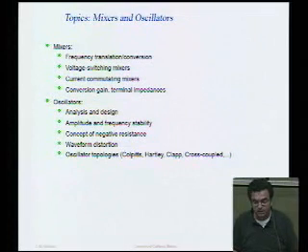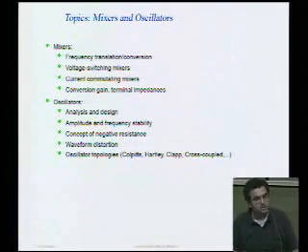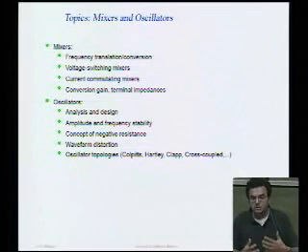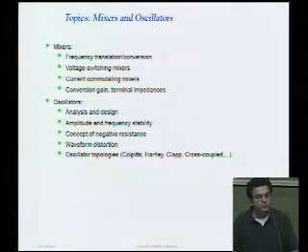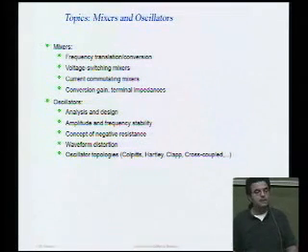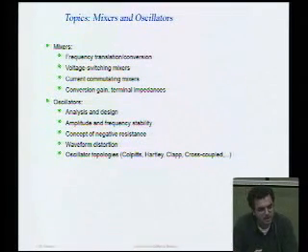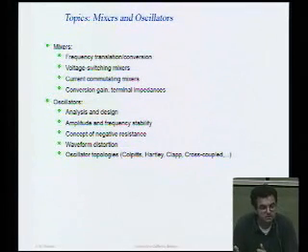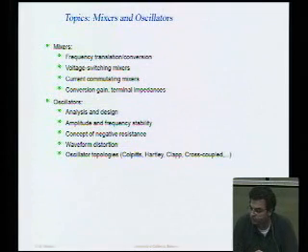We're going to talk about mixers and oscillators. As we discussed, mixers are circuits that perform frequency translation. They're either nonlinear circuits or time-varying circuits, so we're going to have to learn to analyze them. Turns out that SPICE, actually standard SPICE, is not a very good tool for analyzing mixers. It's very slow. There are better tools for analyzing mixers, namely harmonic balance simulators and periodic steady-state simulators, such as Cadence Spectre RF, and that's when we're going to learn about these simulation tools.